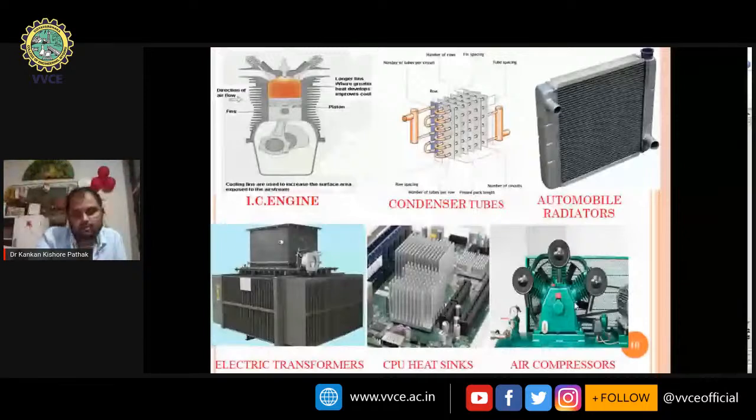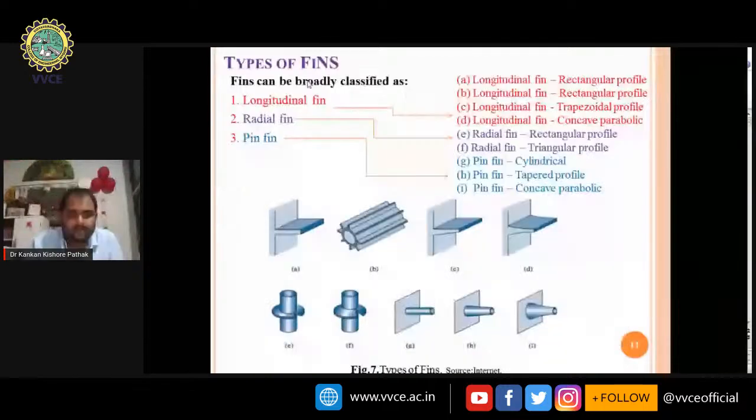Fins can be broadly classified as longitudinal fin, radial fin, and pin fin. Now, longitudinal fins A, B, C, and D are longitudinal fins with rectangular profile, and this is also a rectangular plate oriented radially, but it is considered under the rectangular profile or longitudinal fin only.